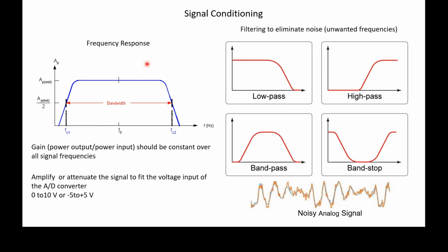You may have looked at specifications for high fidelity amplifiers and seen that they provide you with this kind of graph to show that yes, their system does not provide any distortion by amplifying one frequency component over another. It is flat. We would like it to be flat so that all frequencies between, say, 15 and 20,000 hertz are magnified by the same amount to drive our speakers and so that we hear it properly.